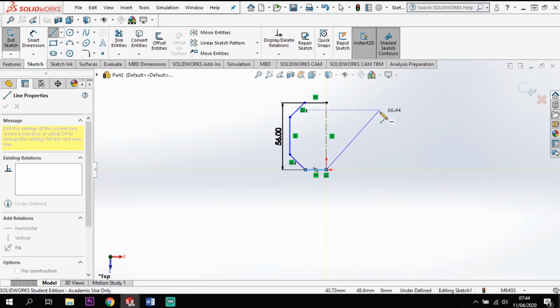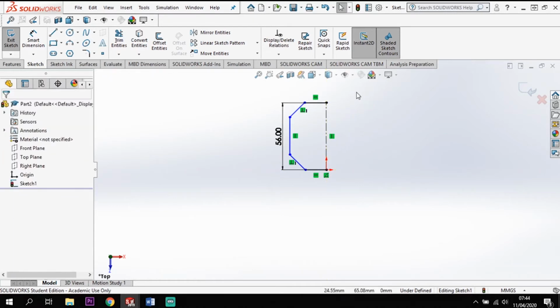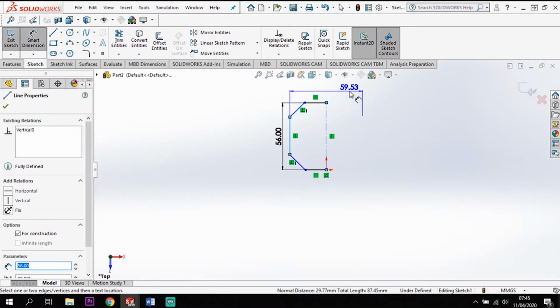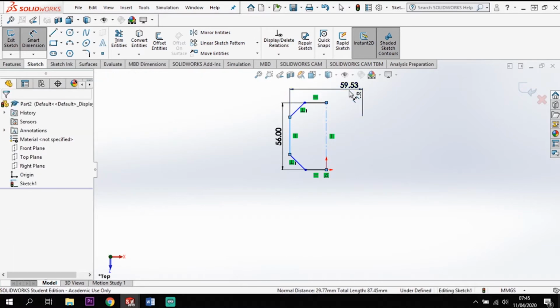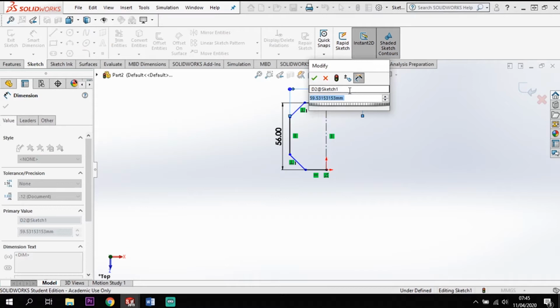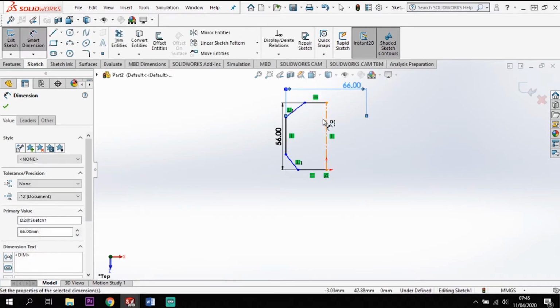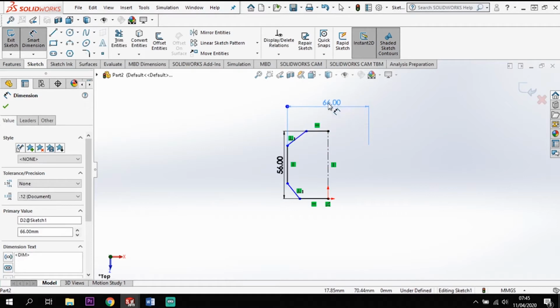So I've just roughed out half of this. Now let's put some dimensions to it. So this outside edge here to here, all the way across, is 66. So you can see that I've just taken that dimension to the centre line, to this line, from the centre line to here, but because when we dimension to a centre line it treats it as a mirror, as we take our dimension tool over this, it will give us the distance from the mirrored part to that.